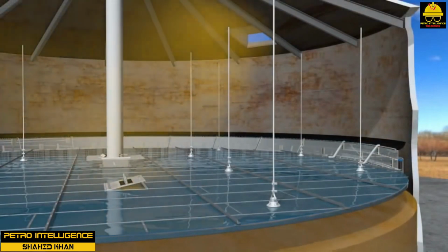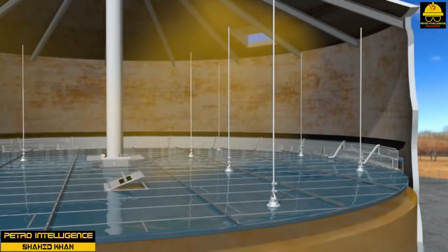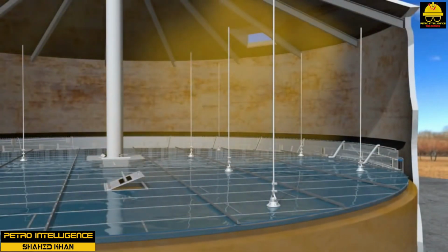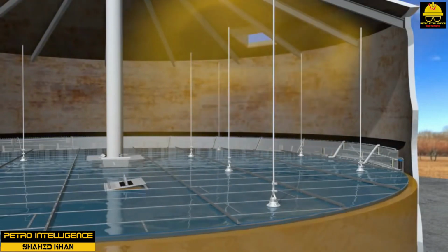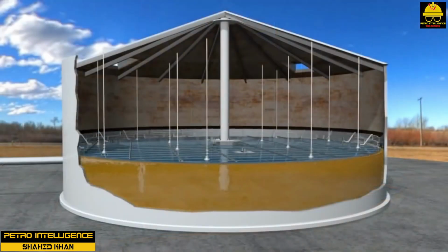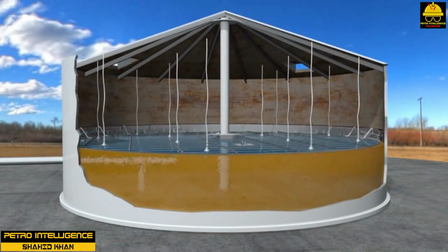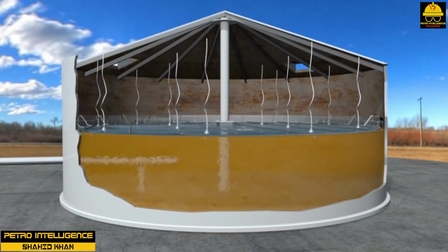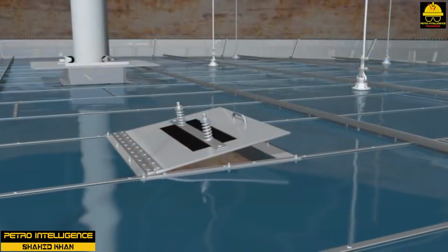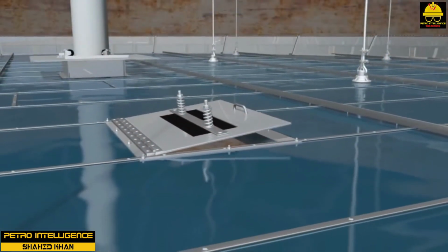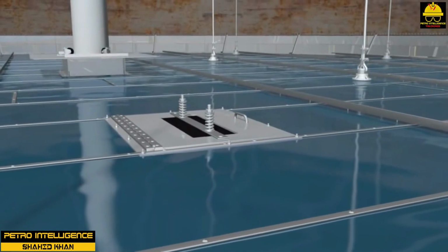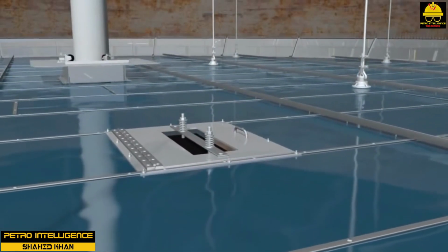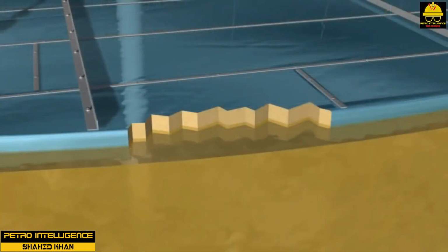John H. Wiggins invented and built the first practical floating roof in 1921. A pan type, it featured a deck of a single thickness with a vertical cylindrical rim at the periphery or outer edge. The deck is coned slightly toward the center and is provided with radial rafters and trusses to give it stiffness. Today, the pan roof is used only in areas of low rainfall because the roof will tip and sink when loaded unevenly with water or snow.